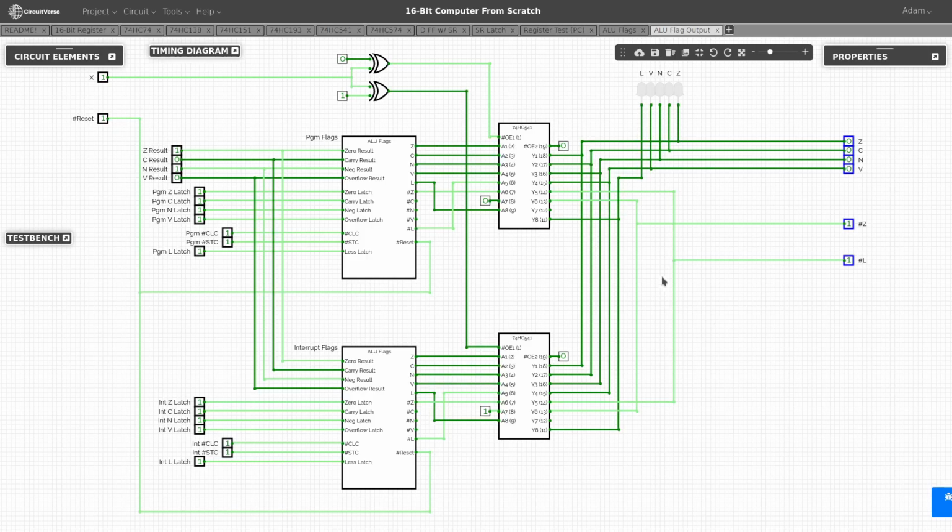Well, I was able to simplify this from 4 line drivers down to 2. That's now 1 for each set of flags, which is an amazing simplification. I did take out the inverted LEDs, and so I'll have a line driver which drives those as well to make sure that I am not putting any load on these signals. And then of course I've got the 6 flags exiting this particular module, and that's going to make life much easier for me when I get into determining whether or not a condition has been met or not, as I talked about in the previous segment.